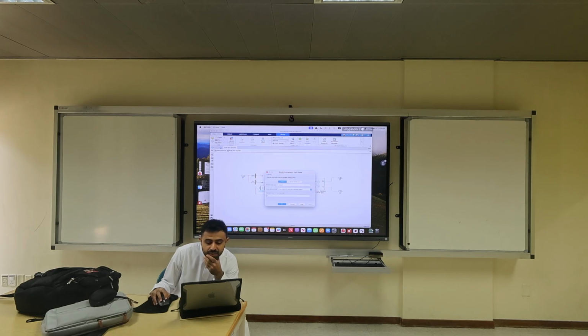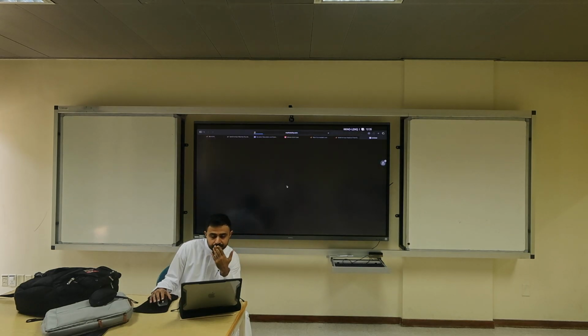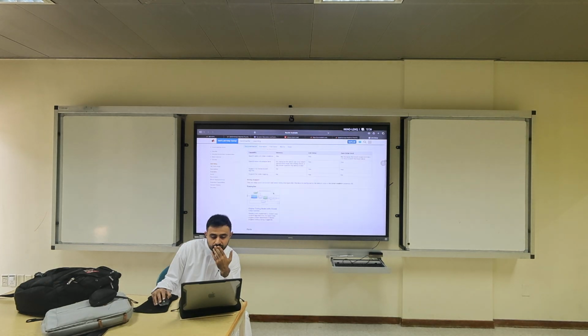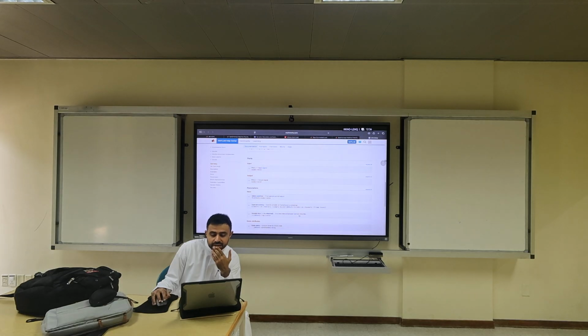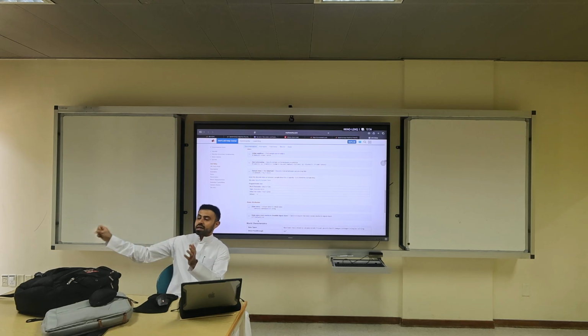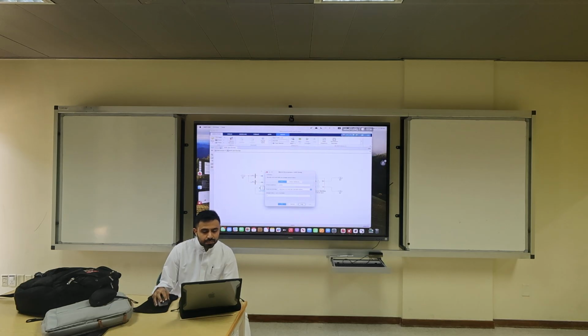No. The delay is the previous sample. This is digital. This means take the previous sample. This is the initial condition, I don't care about it. I care about this sample type. If you put, for example, other values in the delay, such as sample time, the discrete interval between sample time hits, the default value is -1, which is 1 sample. If you put 5, it means you will wait for 5 samples and then take the field after 5 samples.